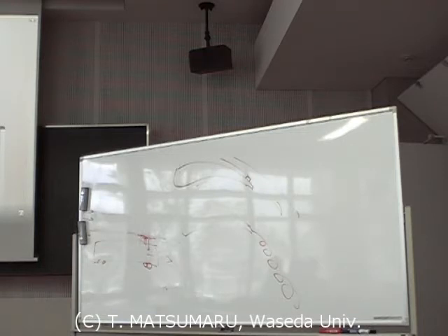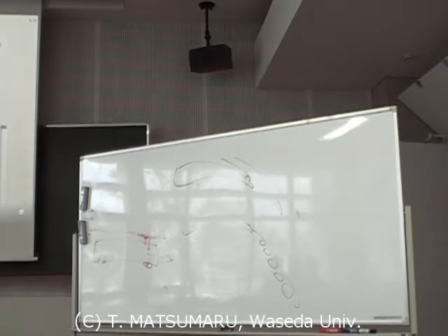Now, why is flow separation bad? Let's consider a basic example. In layman's terms, imagining a basic example like an inverted car wing is quite simple. You can think of it as the flow comes in here, and then we want to deflect the flow up here and end up with it somewhere over there. Now this means we want to keep this flow on here so that it shoots up there, and this flow up here. This flow here is obviously going to stay attached, because it doesn't have an inverse pressure gradient as it's pushing into the shape. This flow down here, though, does have an inverse pressure gradient, which means that depending on the wing profile, you may end up with the flow shooting up over here, which results in a much less efficient wing.